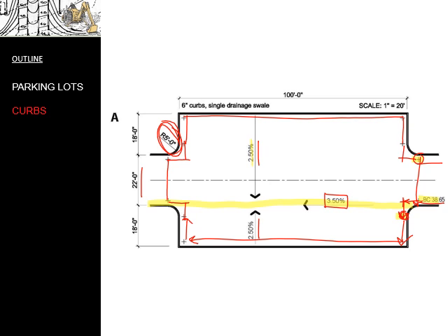To figure out where these contours are going to be, you're going to think about 3 lines running along the length of this parking lot. And just as you have learned to do when you're solving for swales, you're going to use the elevation at one end of the parking lot compared to the elevation at the other end of the parking lot using a specific slope.